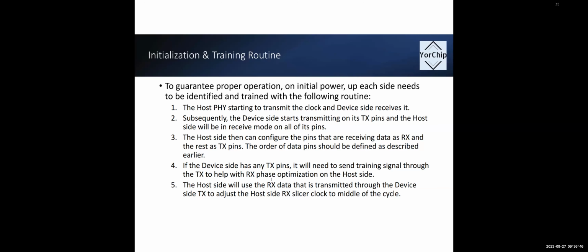I think there's benefit of being DDR because it keeps the quote unquote max frequency on all the lanes the same. I think it would be 1 to 2 gig, but we have to do some analysis to see if, depending on the distance, we can meet 4 gig. So it also becomes a trade-off with the channel distance. It's not as much the loss as it is the latency, the quality of the clock going there and how much that quality degrades, and then when it goes through the system and comes back, the data recovery. So there's a bit of involvement there, but we want to define a minimum for it.